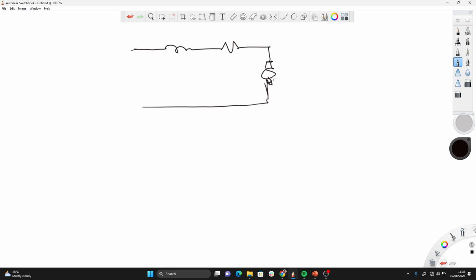When I add an external resistance like this, I have my RF here, I have my RA here, and I have my R external here. I have my VA. The only thing that changes in the equation is when I was finding my E. In the first case, E is equal to V minus IA RA prime. That RA prime is this RA plus RF.